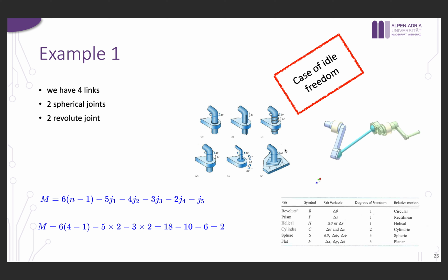And as I said at the beginning, when it comes to degrees of freedom, the first thing to look at is: is it a closed loop? If yes, it has 1 degree of freedom. But even if it's not a closed loop, it's an open loop, but we have only 1 actuator connected to this mechanism, and this 1 actuator is enough to move the whole mechanism the way it's supposed to move, then we have 1 degree of freedom. Okay,